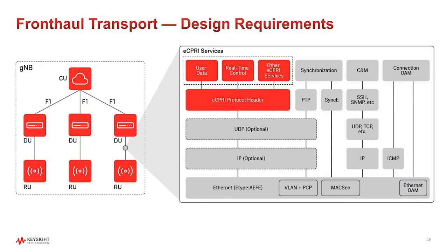The existing CPRI does not scale cost effectively for 5G because of its use of much larger spectral bands and massive MIMO, etc. The CPRI Corporation has created an enhanced CPRI, or eCPRI, protocol that scales bandwidth about 10 times more effectively than 4G CPRI, thus optimizing the transport bandwidth.